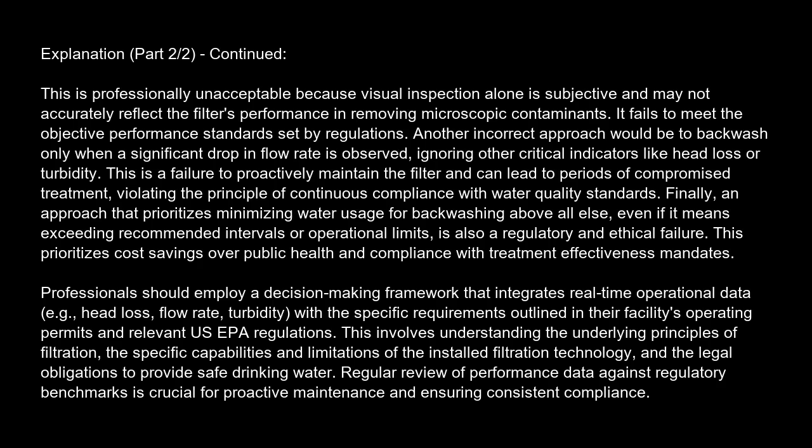Another incorrect approach would be to backwash only when a significant drop in flow rate is observed, ignoring other critical indicators like head loss or turbidity. This is a failure to proactively maintain the filter and can lead to periods of compromised treatment, violating the principle of continuous compliance with water quality standards.